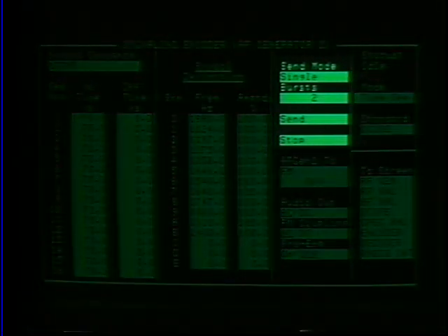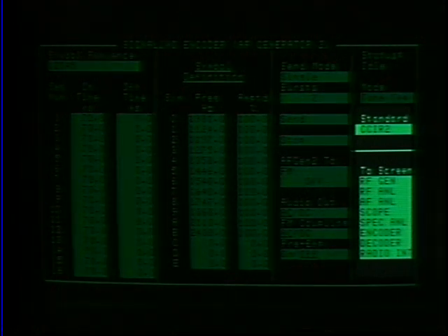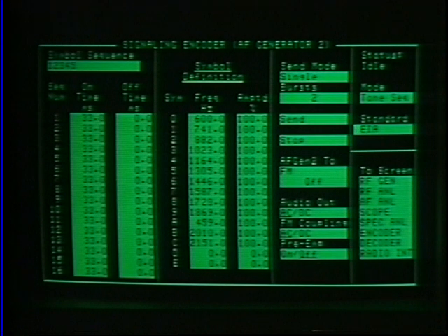Your tone burst can be sent out single, a variable number of bursts, continuously, or manually step through one tone at a time. Built into the 8920 are a number of international tone sequential signaling standards such as CCIR, CCITT, EEA, EIA, Euro, Natel, and ZVEI. Simply choose the appropriate standard and the 8920 will automatically update its tones.